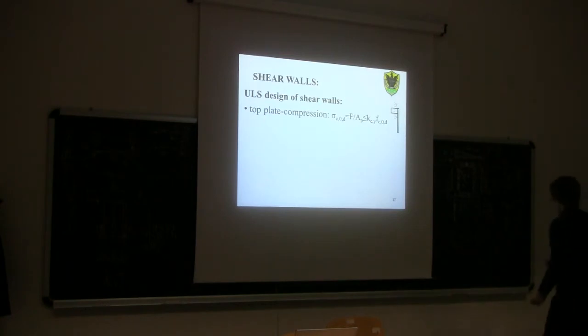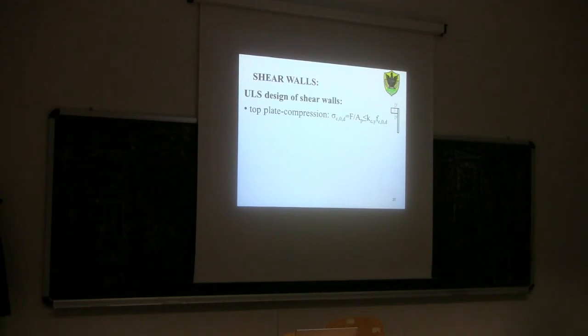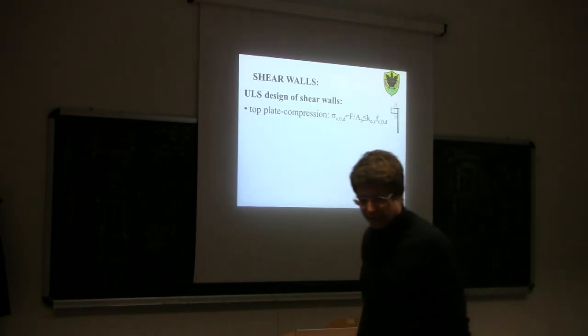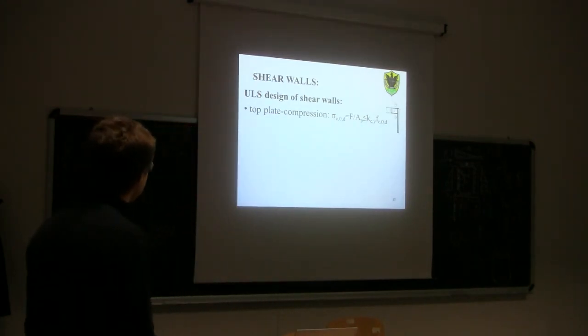In other words, to have a vertical buckling, it would mean that the sheathing must be distorted this way. This is not possible because the sheathing is very stiff in its plane. Okay? So kcy is the reduction factor due to flexural buckling. If you go and see the lecture that we had several weeks ago, we were talking about buckling, flexural buckling.